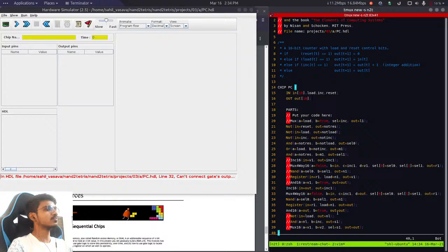Because this will create a loop, and we don't want to do that, but we need the incremented value of the output. So how are we going to do that? Let's see. First of all, we are selecting based on the value of selection bit 0 and 1, either the false input, the incremented value, or the output inside R1. But we already saw in the last stream that it was not working, even though we were selecting properly. The R1 didn't get the value of these inputs.